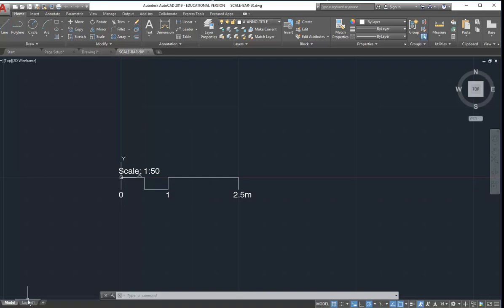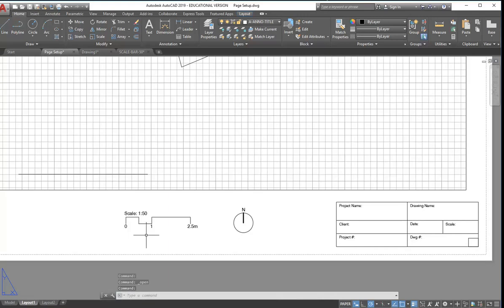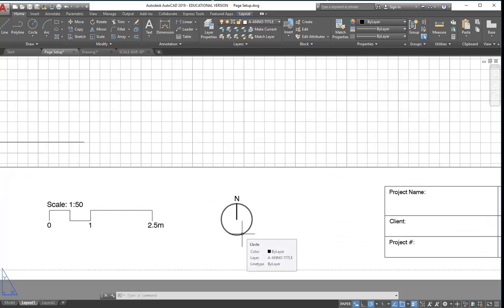So say you've just had a file, and see what a lot of people will do to make a block, instead of using WBlock, they'll just save it as a new file, which works if you've drawn it in model space. So they might have drawn a kitchen sink or something. If you do Save As from paper space, then it generally won't work if you try to insert that into another file. If you want to insert into another file, use WBlock, that's the way to make sure.